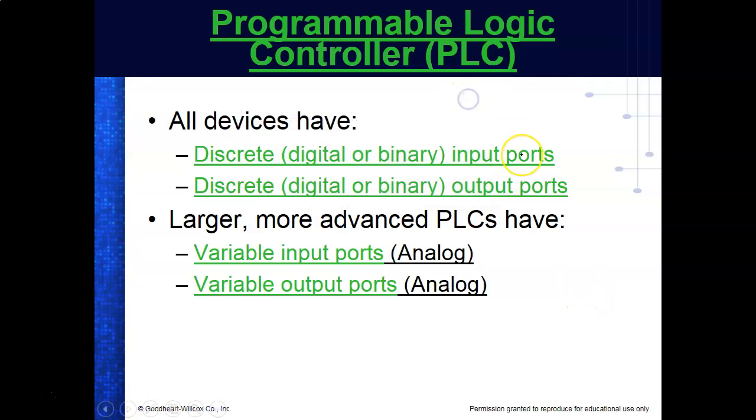What's so neat here is that you're literally reducing the size of a circuit or a program, which really comes into play. The book calls it discrete, binary, or input ports. Most of your new PLCs call this bool, for Boolean, and if you see that, it means this is discrete, or ones and zeros.